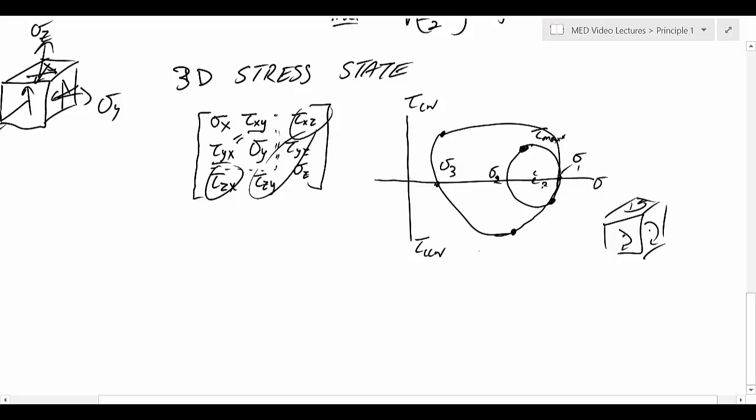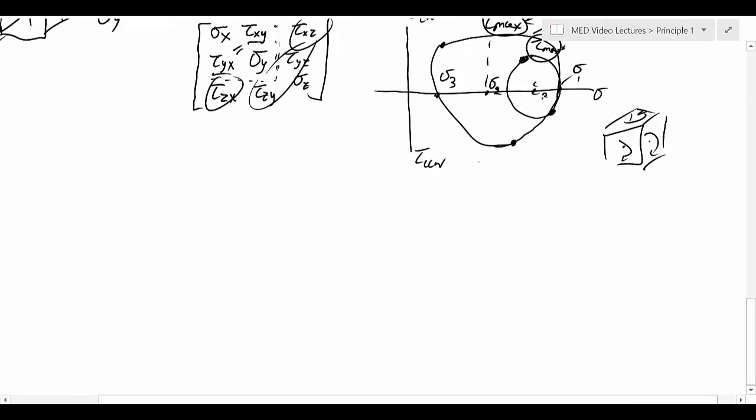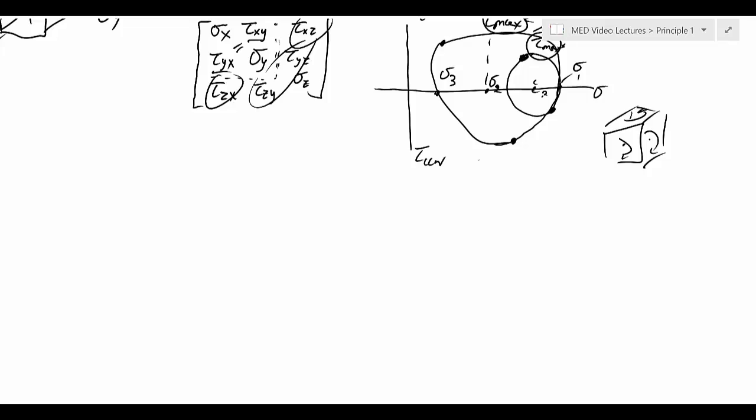So as you can obviously tell from the circle, if we found the center between those two, this is the actual maximum shear stress. So if we believed that this was our maximum shear stress and we went on a failure theory that said it breaks on maximum shear stress, we would have significantly underestimated. Now, for most of what we'll be doing in this class, we're concerned about plane stress. Because bending stress, or normal stress due to bending, tends to be maximum away from the neutral axis.